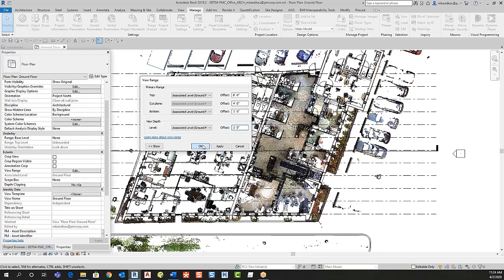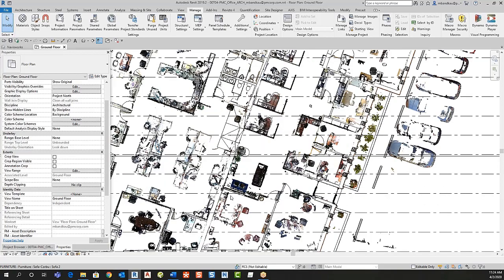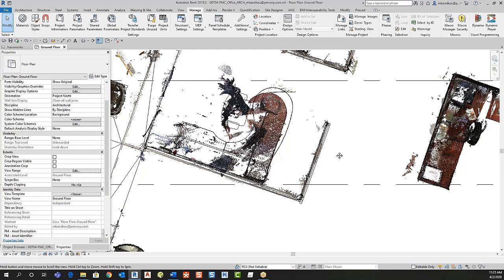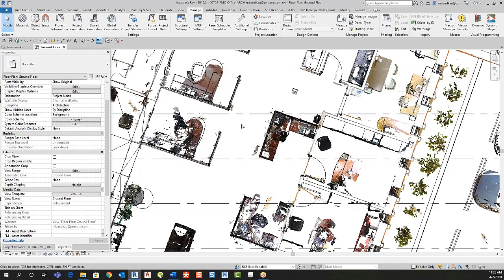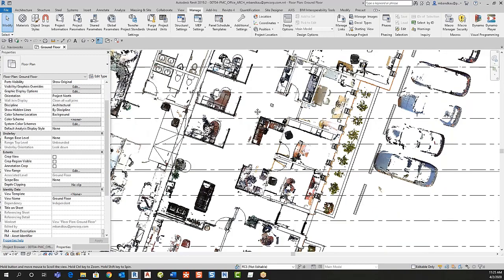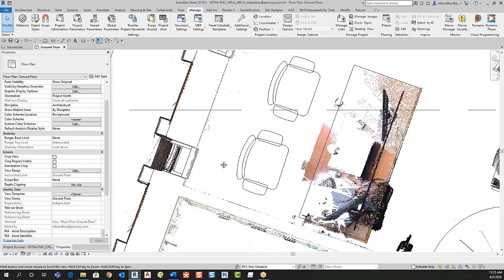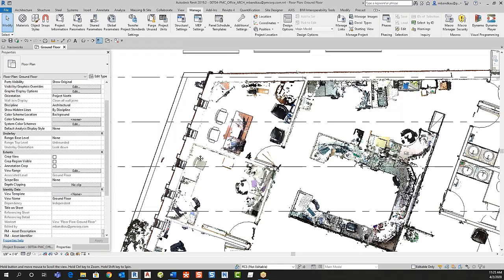Now you'll see that cuts out the carpeting in this east wing, and now we're just seeing everything that occurs above the 1 foot view range and below the 8-foot view range. So this is good for quality check if we're in a model and we want to look at strictly walls and we don't want that carpeting or any other noise that may be captured. We can see here there's some casework and some countertops. See the matching on this water closet.